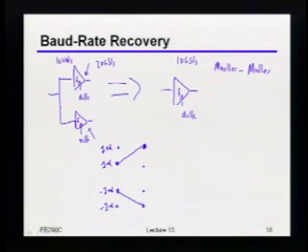The analog voltage is not actually constant, okay? Well, if the analog voltage is not actually constant, then in principle you can actually get some timing information, right? Because as an example, if I sample that analog voltage there versus here, I'll get a different answer. So the way you would typically do a baud rate recovery loop with something like this is you're basically looking for some kind of threshold that's sitting in between the 1 plus alpha level and the 1 minus alpha level, okay?